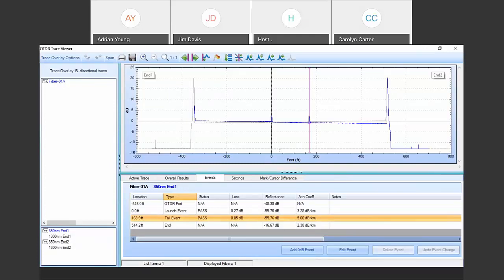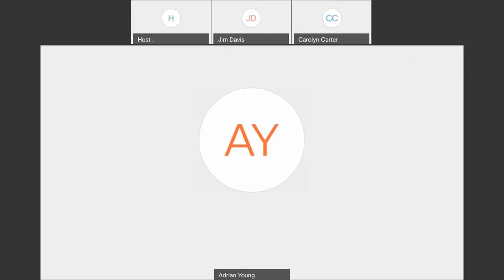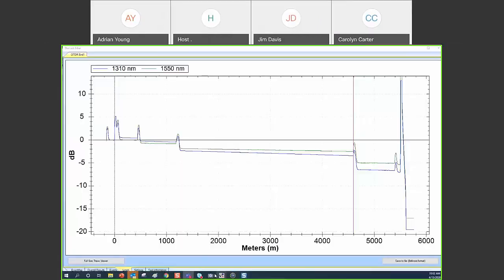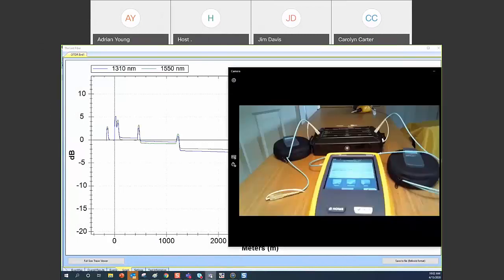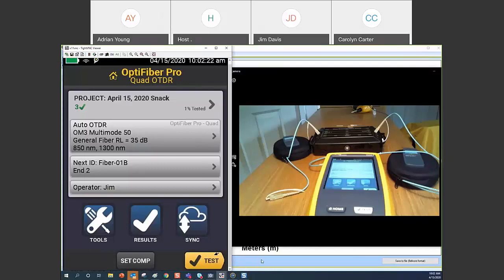So what is the story there? Well, the story is the application will work, but your contractor has not met the requirements for that installation. The other thing that gets a little bit touchy as well is if you start concatenating fiber links, that's when you're going to start having problems. Right, and I'll add in, Adrian, another thing that can happen is if a couple of years down the road, you decide to go for an application that requires tighter limits and you don't really know whether or not you can meet those, that's when you can run into problems as well.